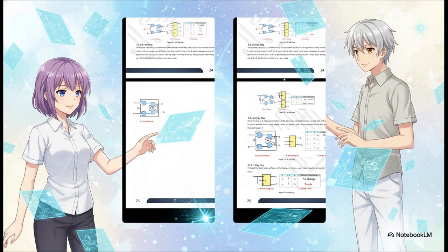And you know what? That toggle function was so useful, it got its own specialized stripped-down version, the T flip-flop. Its entire purpose in life is to toggle. If the T input is a 1, the output flips on the next clock pulse. If T is 0, it just stays put. It's a perfect example of engineers creating a very specific tool for a very common job.